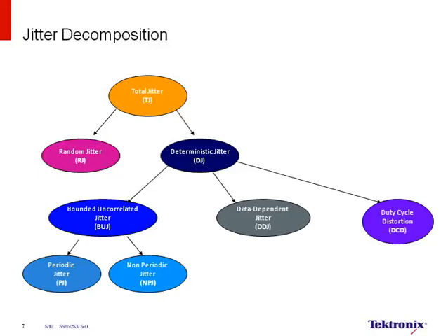Okay, the next question here is, RMS jitter may depend on: 1, PLL setup, analog or digital; 2, phase detection circuitry; 3, phase noise of the active device; 4, bandwidth, LC circuit, Q of L and a varactor C or digital delay; 5, clock embedded in data and recovered, or clock locally generated independently; 6, phase noise is a function of offset from carrier frequency.